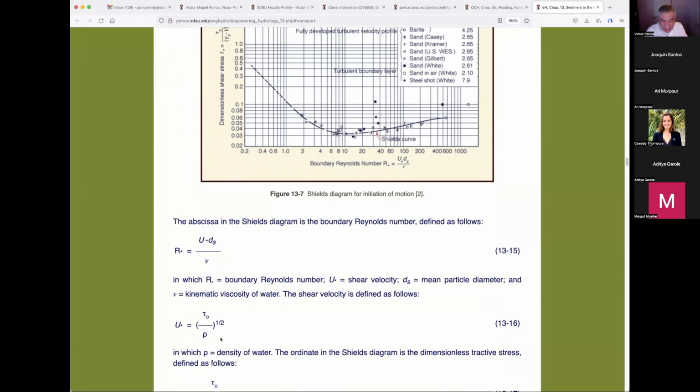And I realized that the shear velocity is a way of expressing the velocity, only that affected by a frictional constant or a frictional factor. And the frictional factor turns out to be a readily identified frictional factor, which is exactly 1/8 of the Darcy-Weisbach. So why Darcy-Weisbach over here? Aren't we used to Manning? And the answer is no. There are actually 5 ways to express friction in open channels. And I'll endeavor to get back to that later on.